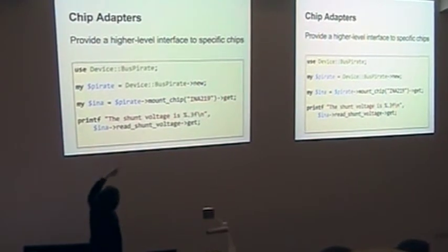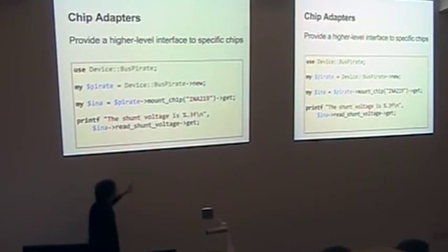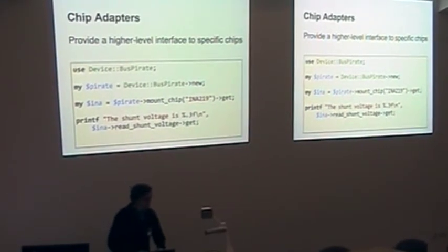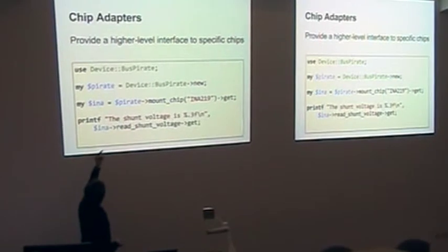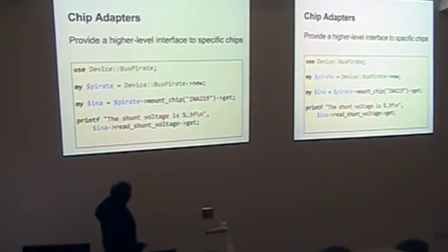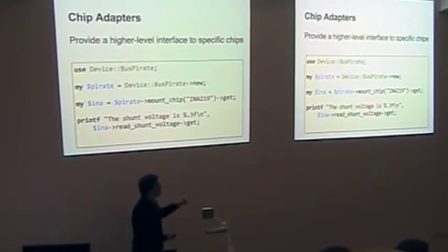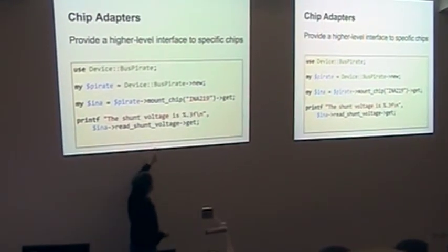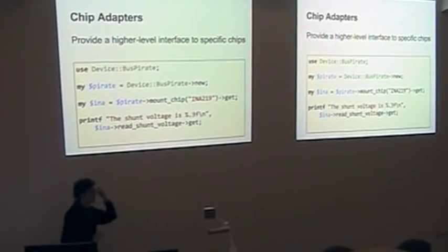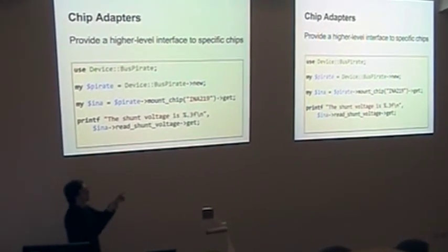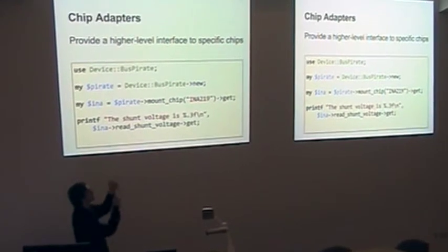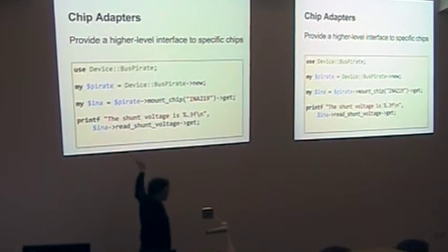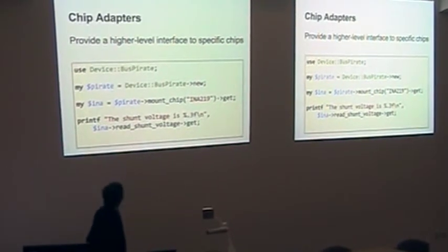But that was ultimately what I was trying to aim at, because trying to perform this operation by opening the text console and manually typing things in, you have to do, I think it's either 6 or 7 commands over the serial console to get it that far. And that gives you the voltage once. And then of course it just writes out a raw hex number, and you have to think to yourself, right, well these bits are this field, and that bit's that field, and I have to multiply that by 4, but 2 if that register was there. It's horrible. So this abstracts the whole thing away, makes it very nice.